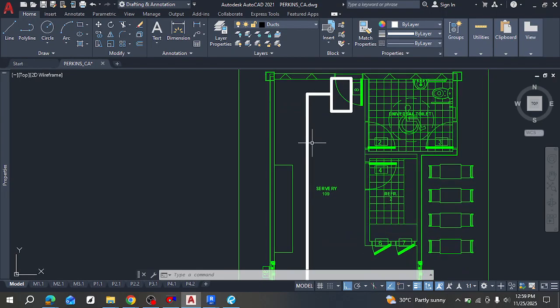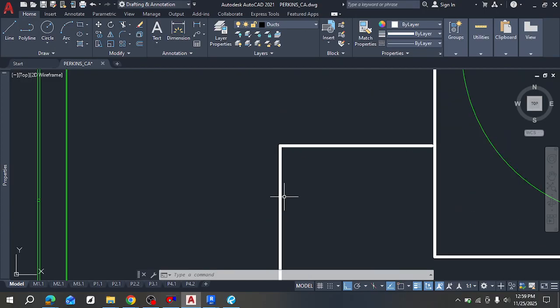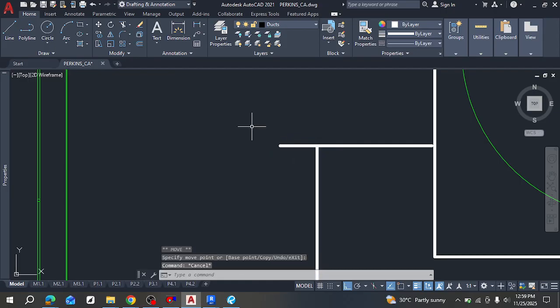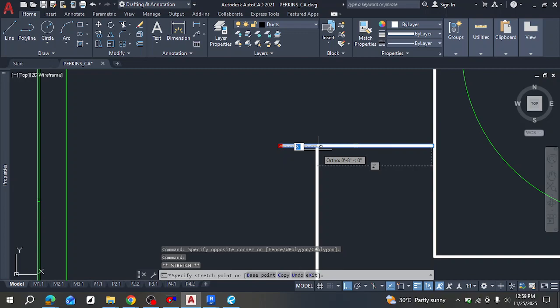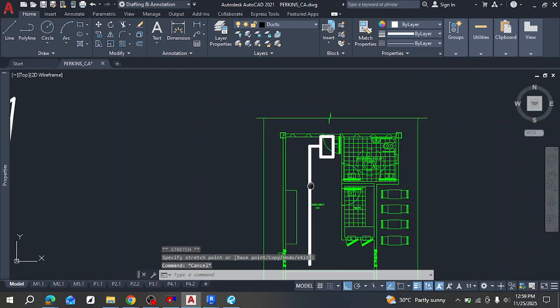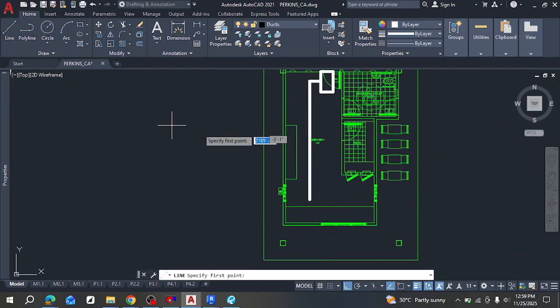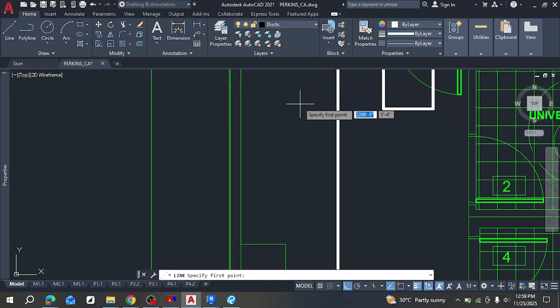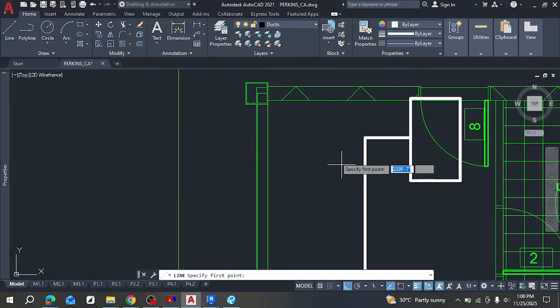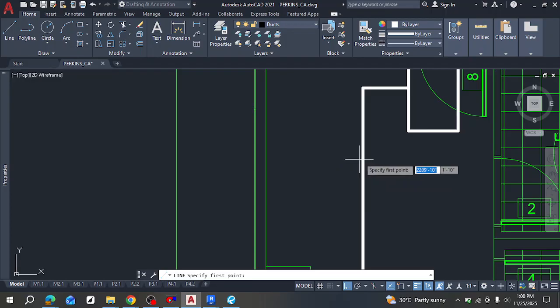So now I have, what will I call it? Let me shift this a little. Yes, I have branch or flexible ducts. So I'll shorten this line. Okay, so now I'll still use line for that. Now I want to scatter that 1200 CFM in this space. I like putting my register close to the wall. So this will be here.